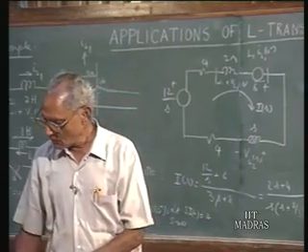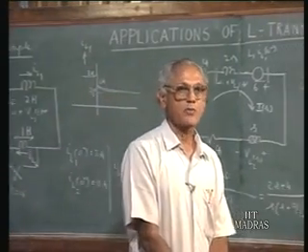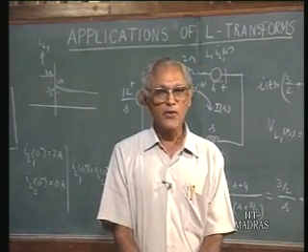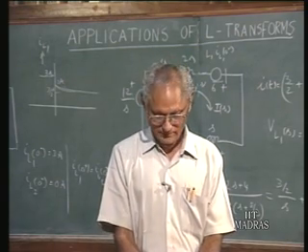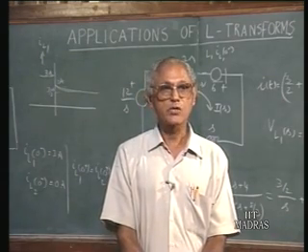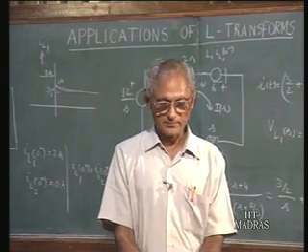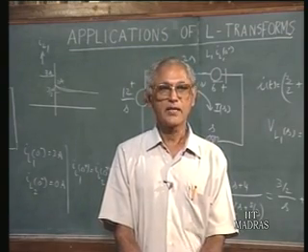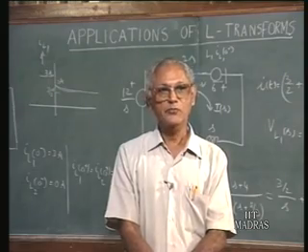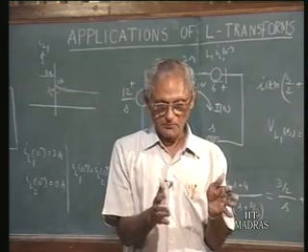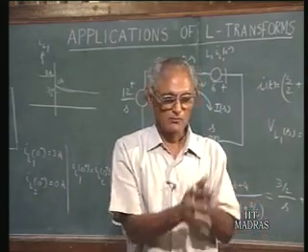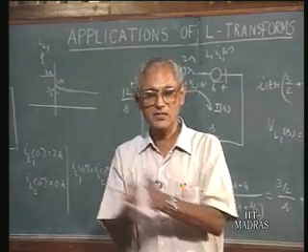But at this time, from what we have seen, let us now see what are the advantages of the Laplace transform domain in the transient analysis of electrical networks. We find there are a number of advantages compared with the classical differential equation approach. First, when you have functions of time which are discontinuous or which have discontinuous derivatives, like your step function or ramp function, then the Laplace transforms of these time functions turn out to be simple expressions, whereas in the classical differential equation approach, suppose the function is described by different analytical expressions in different regions of time. So, you have to find the solution for one interval of time, find the final solution, and fit this up as the initial condition for the next interval, and so on and so forth.